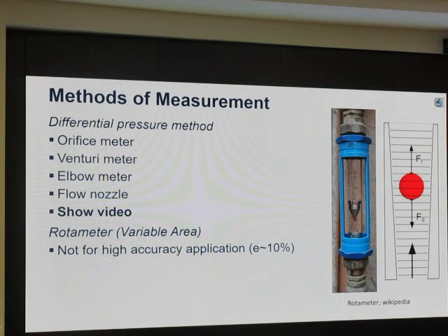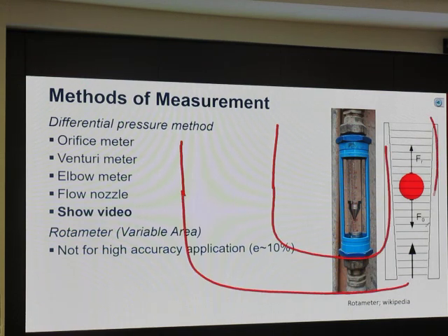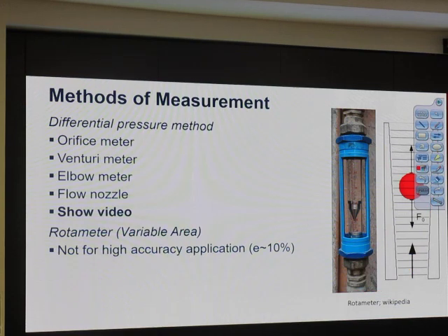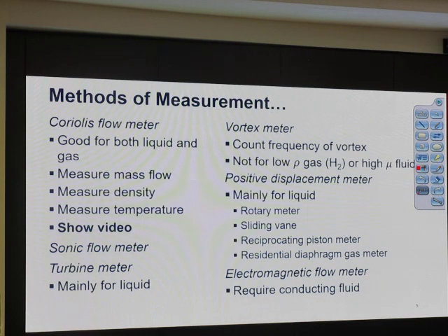So if we buy a bigger unit, what happens? Okay, we have a bigger unit. The pipe is huge and it vibrates. So when the pipe is huge, the velocity that goes through is not that much. Okay? When we don't have much velocity, then I think there will be less error. The range of which one to buy, you can look in their website. Depending on what kind of flow rate, then you look, okay, for this flow rate, use this flow meter, we have that much error or something. It is already tested and documented.